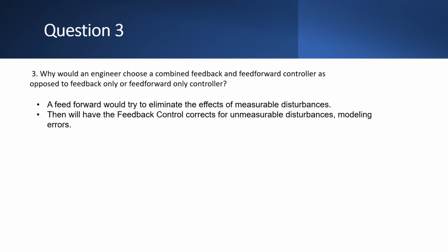If we were to, for example, just use feedback by itself, although there are some advantages, like corrective action occurs regardless, without requiring knowledge about the process, there are disadvantages on its own, like control takes no corrective action until there is a deviation, and control is incapable of correcting a deviation from set point at the time of detection, and theoretically is not capable of achieving perfect control.